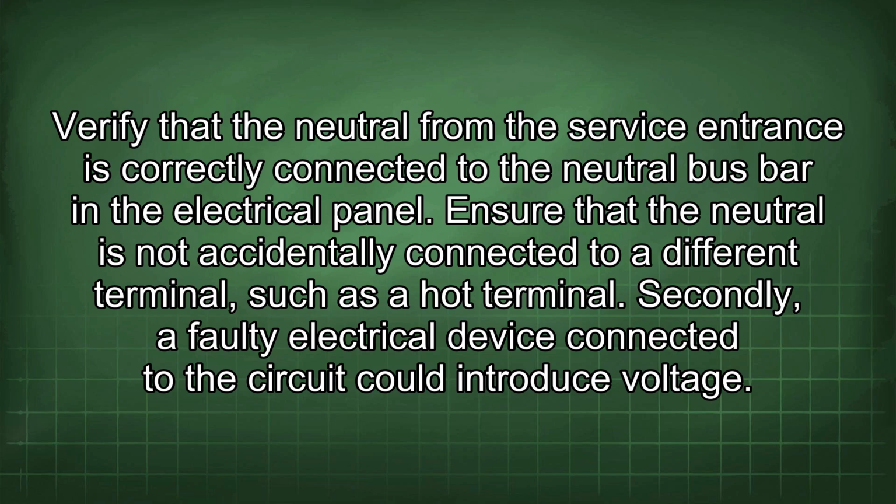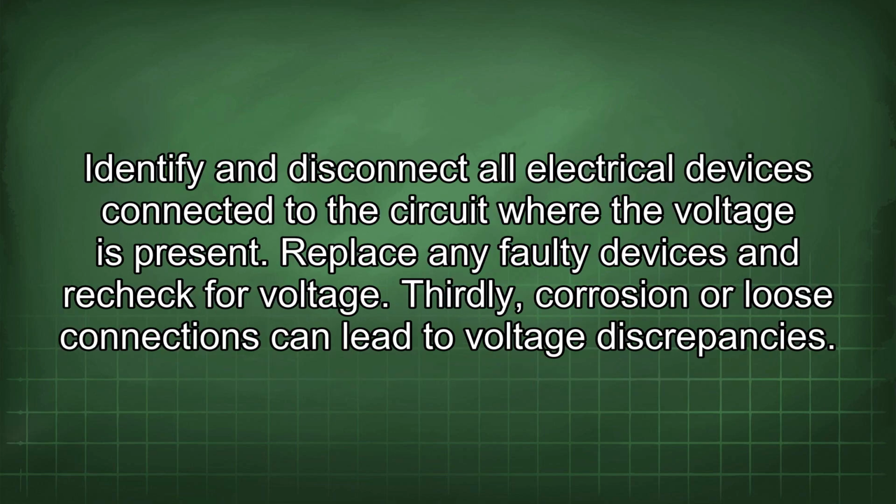Secondly, a faulty electrical device connected to the circuit could introduce voltage. Identify and disconnect all electrical devices connected to the circuit where the voltage is present. Replace any faulty devices and recheck for voltage.